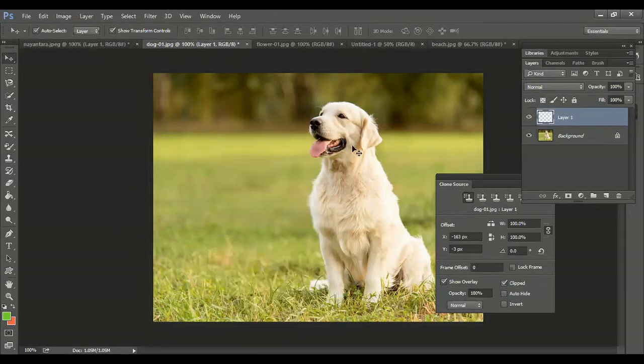If you want to make it 50% smaller, here you can see 50%. I'll put it 50. So horizontally, it will copy and make it smaller, because W is 50 in the X direction. So now it will copy, Control Alt and select.